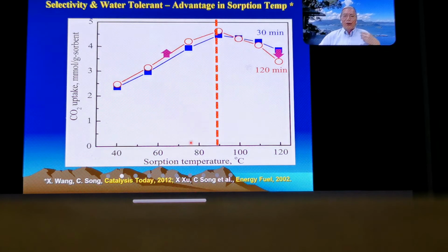And when we do this type of CO2 capture using this molecular basket sorbent, we capture the CO2 in an amount which is an order of magnitude higher than the conventional solid materials, which is why the conventional materials are not economical for use. Another reason that conventional solid materials such as carbon or alumina or zeolite cannot be used is that they absorb moisture first before they can absorb CO2, so you have to separate the moisture. But we designed this material, they can capture the CO2 up to 15 to 20% by weight. So you get high capacity.